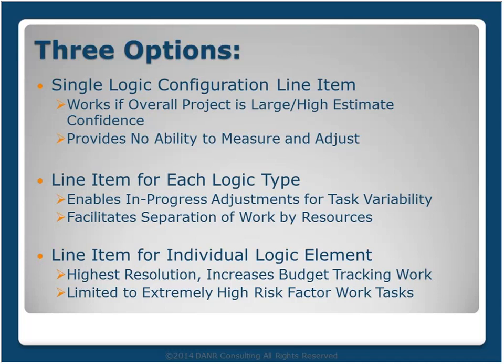And the other benefit of that approach is that if you've got different team members working on different logic types, for example, let's say that you've got one team that's doing all your safety interlocks and another team that's doing all your advanced control algorithms, then this strategy provides a natural separation of those work activities. The final option is to list every individual logic element to be configured. So in the example, there were 5 logic sequences planned, so we would actually have 5 line items, one for each of those individual sequences.